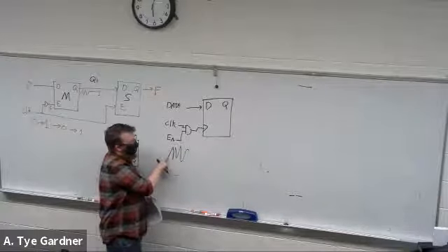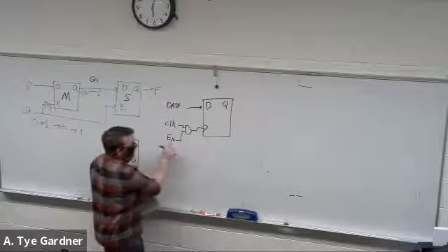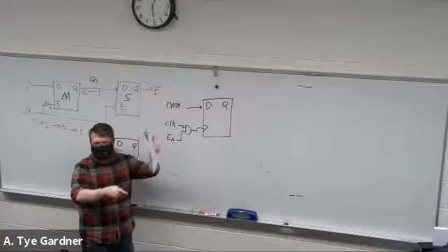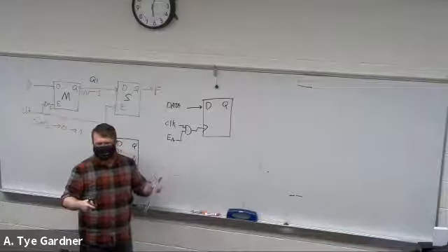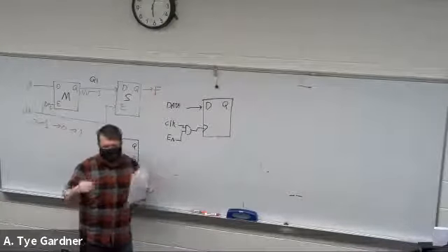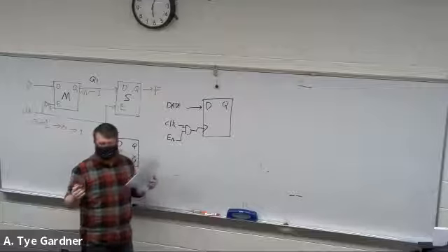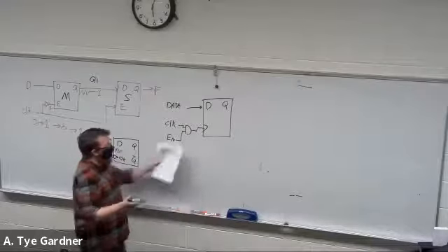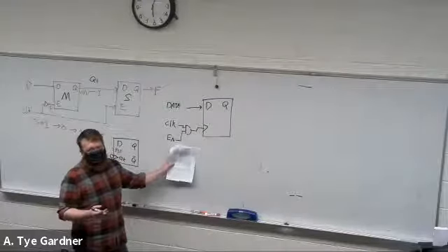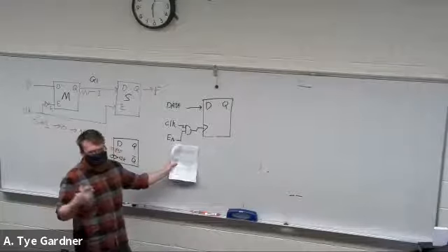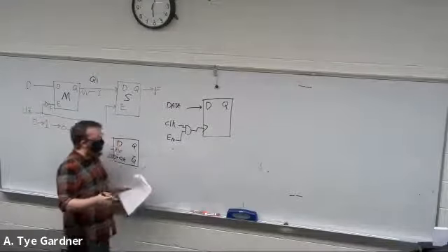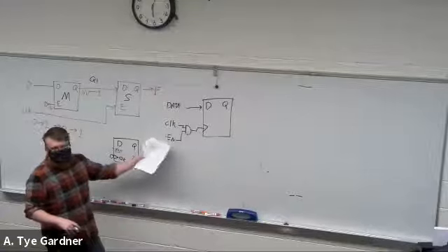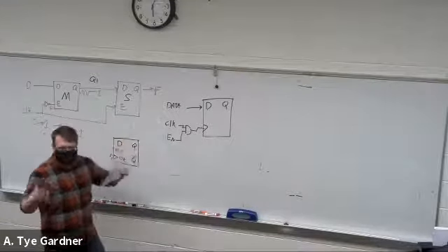In fact, it can be an issue because you can have a very close switching of the enable coming on and the clock coming on and the enable going off, and it's thinking it's clocking at twice the speed. And your circuit will look like it's working because it's clocking stuff in way too fast. You're like, what is going on? So this AND gate turns out to be not a great way. This is a gated clock. You're going to want to know that term, gated clock, because I'm going to ask an exam question about this, almost certainly. Sometimes I forget, but I'll try. It's bad because you don't know if both the clock and the enable can function as a clock.